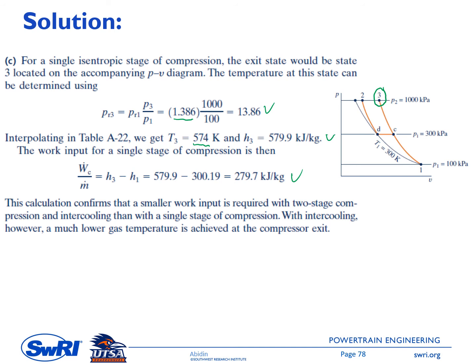Okay, so you can see in here that this simple example confirms that using two compressors plus an intercooler requires much lower compression work compared to the one using only one compressor. So for sure, from another perspective, like the economic perspective, the system with intercooler and two compressors requires more capital cost.